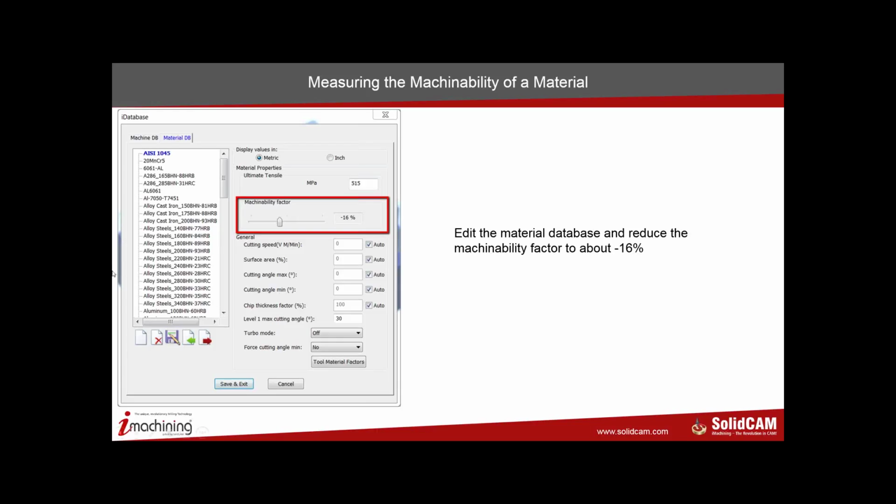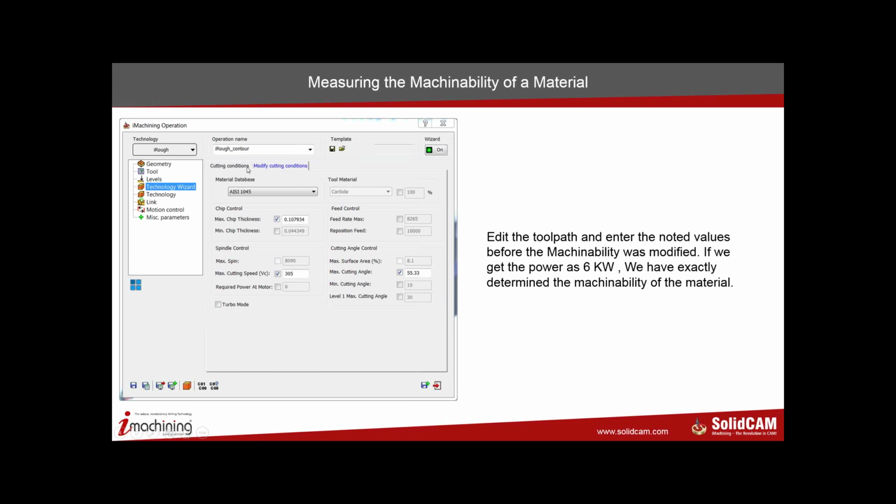So I come to a point where I stop the slider at minus 16%, save and exit. I go back again and edit the toolpath, and I go back into the cutting conditions. Remember, when you move the slider down to minus 16%, iMachining automatically recalculates everything to the new minus 16% parameters. So it will always show you a much lower spindle load, but that's not what we want. We want to know if that machinability factor of minus 16% is right or not.